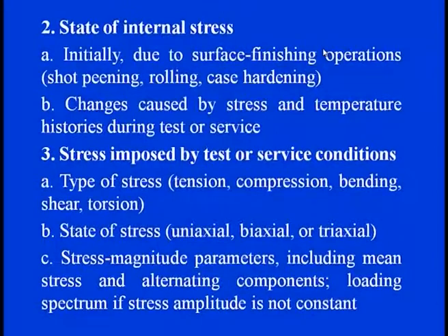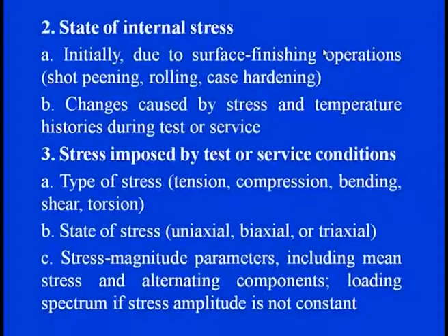So certainly it has a clear impact on the material damping. The third factor is the stress imposed by any service conditions or test condition, like the various types of loading conditions, and as a result the various types of stresses, like uniaxial stresses, tensile or compressive, shear stresses or torsional stresses, and bending stresses, which is nothing but the combination of tension and compression.